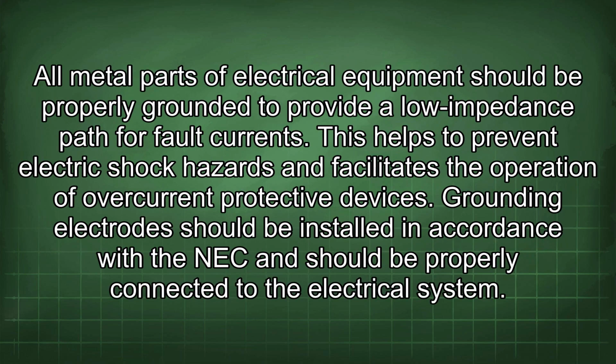Thirdly, grounding is an essential safety measure in wet locations. All metal parts of electrical equipment should be properly grounded to provide a low impedance path for fault currents. This helps to prevent electric shock hazards and facilitates the operation of overcurrent protective devices. Grounding electrodes should be installed in accordance with the NEC and should be properly connected to the electrical system.